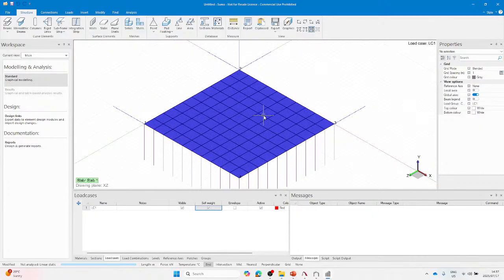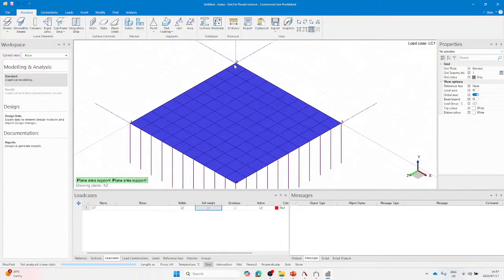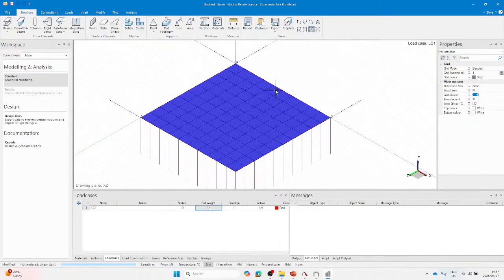and then switch to the discretized model. If we look at this, if I count these 1, 2, 3, 4, 5, 6, 7, 8, 9, 10, definitely we have 10 shell elements in the horizontal direction as well as the vertical direction, because the mesh size is the same as how much we spaced our nodes in frame, right? And then from there, we can apply that load that we applied in the middle of our slab, similarly to what we did in frame.